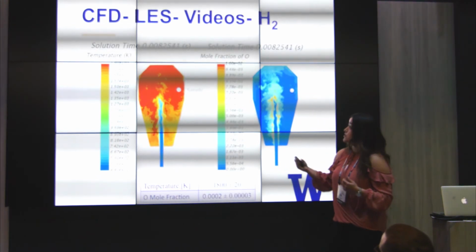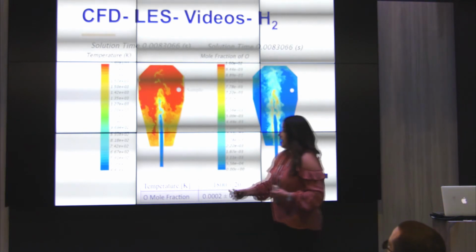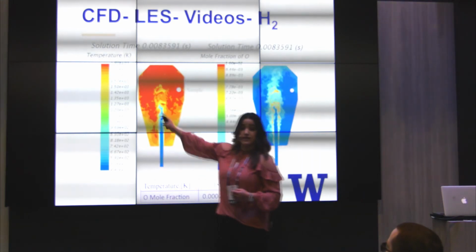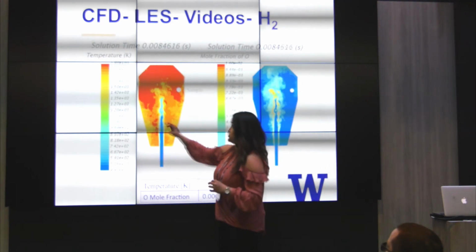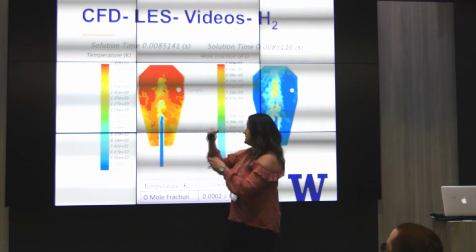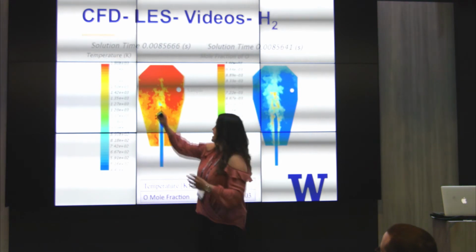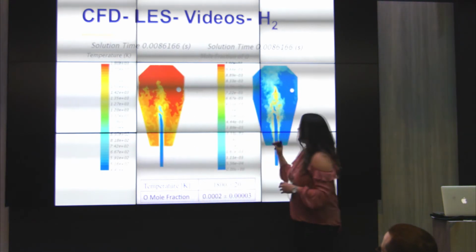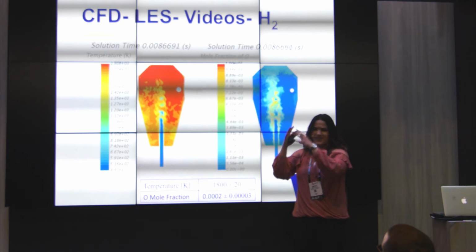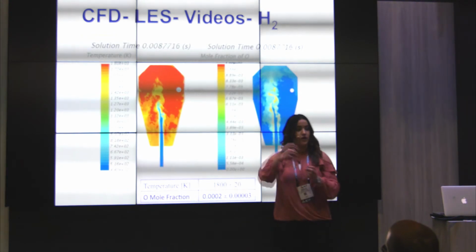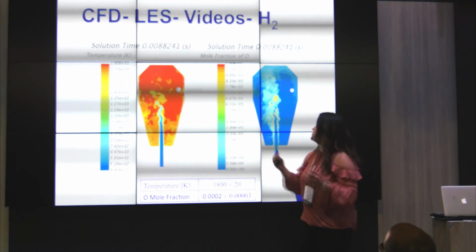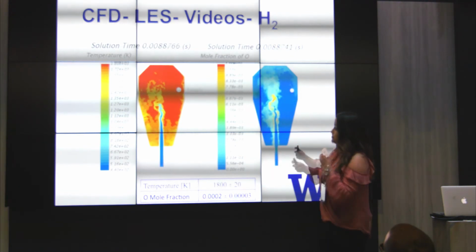Now this is a transient problem. We get a lot more detail about the structure of the fluid at the jet and in the recirculation zone. We can see these eddies rupturing from the jets, and here you can see that the dome doesn't exist anymore. It's really pockets of high O radical that's dissipating in the jet-steered reactor and in the recirculation zone.